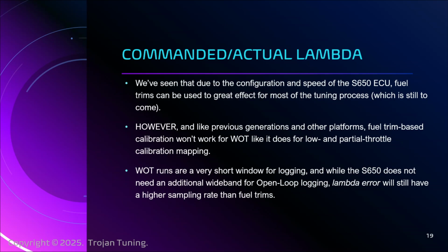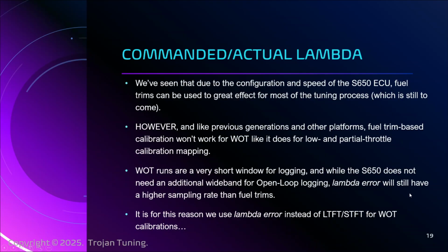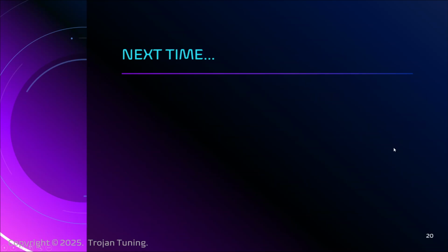This won't mean a lot to you now, just for other tuners maybe who are following along. We still have to do commanded-versus-actual calculations on our fuel trims, to account for fueling errors up top. So just a little bit of trivia. If this doesn't mean anything to you right now, that's okay. We're going to unpack it a lot more in the future. But yes, lambda error is still used in addition to the LTFT and STFTs.